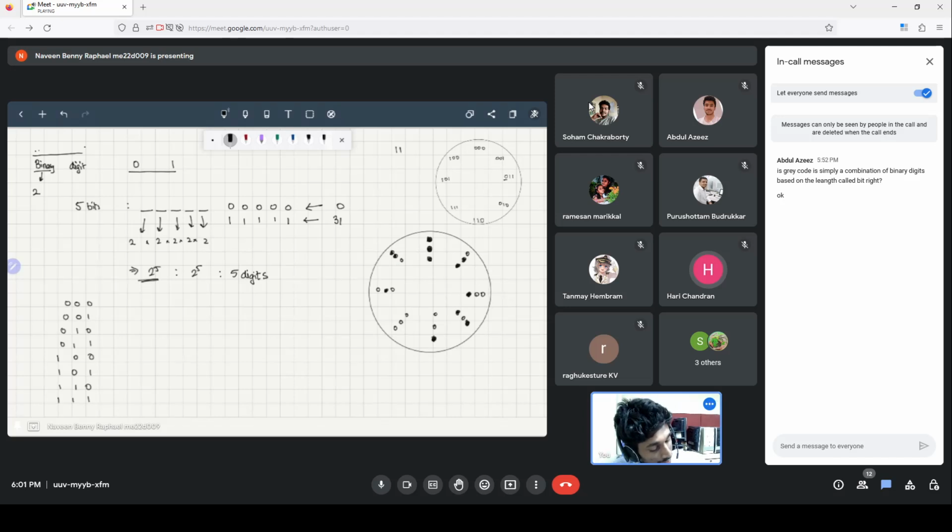Now I'll put a light emitter in the front, and I'll have 3 light sensors right behind each of the holes. Okay. So the thing will look like, if you look at the side view, there's a light emitter here, and there are 3 light sensors here, and these light sensors will be positioned so that they'll only get light from each specific hole.